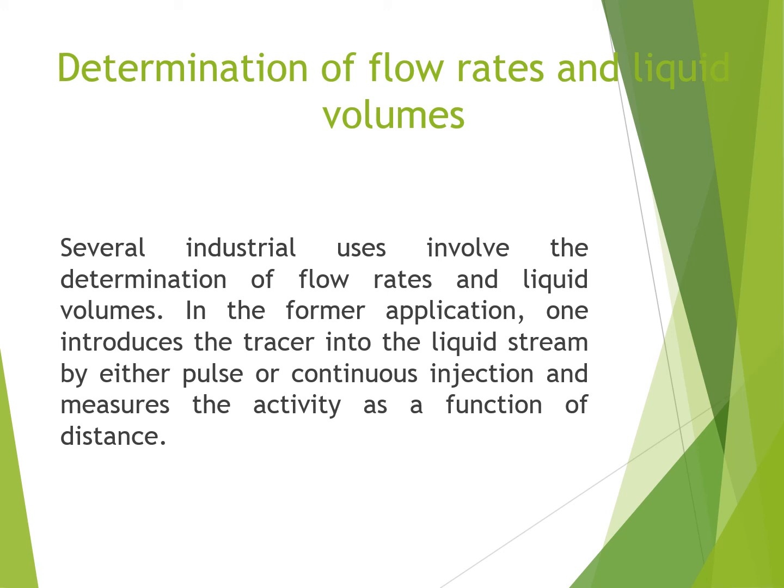We can introduce the radiotracer along with that liquid, and in this way we can determine the activity of the radiotracer. The radiotracer can be introduced into the liquid streamline by different processes like injection or by the pulse method, and in this way the activity can be measured as a function of distance.